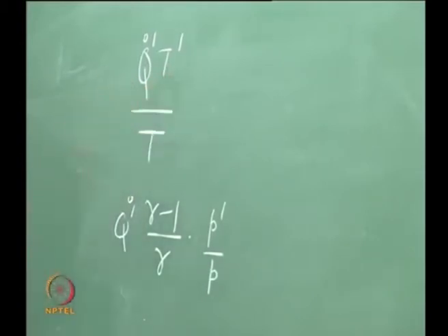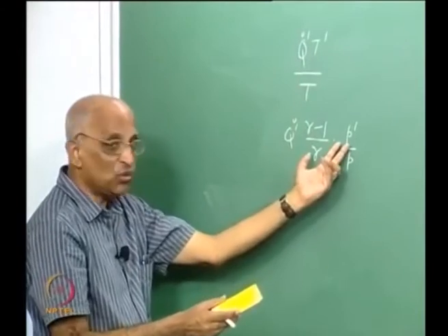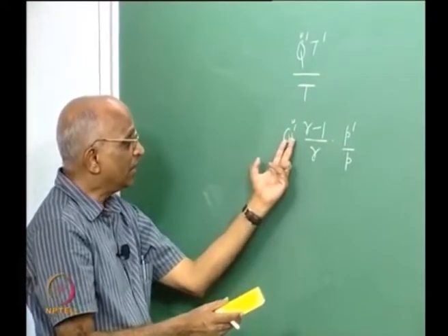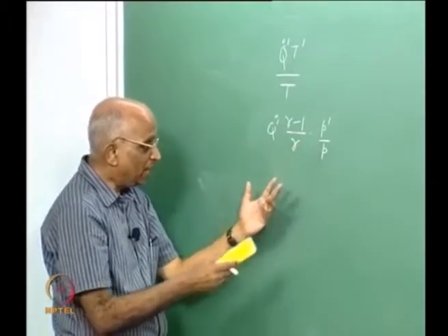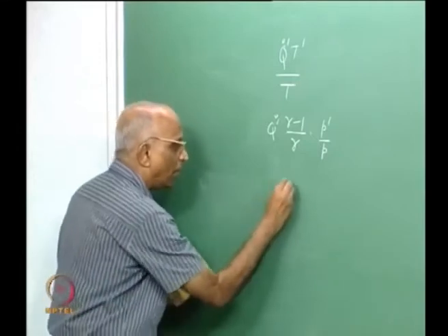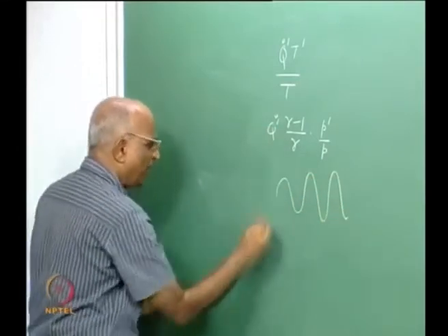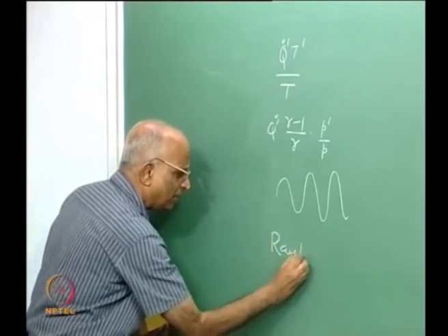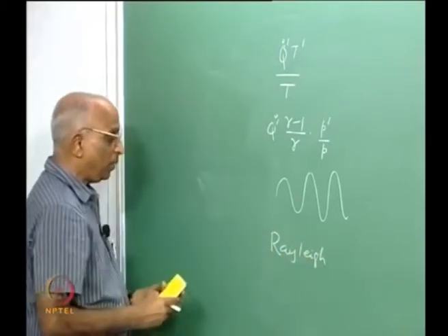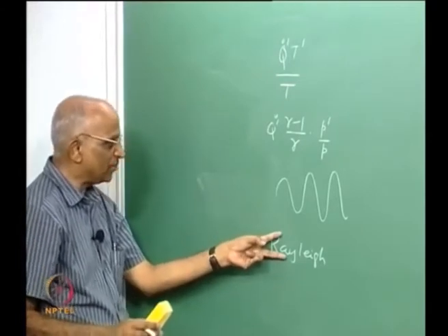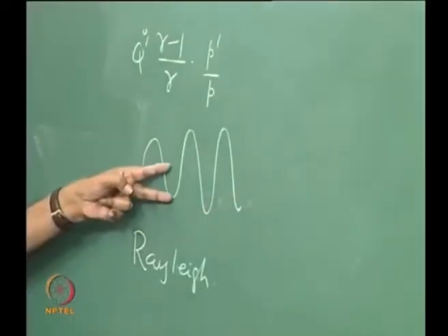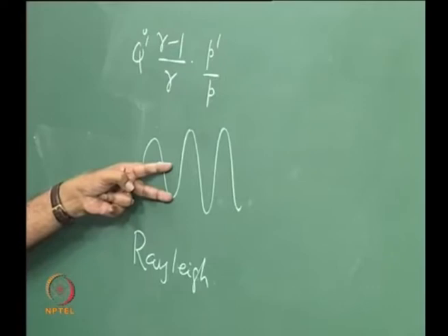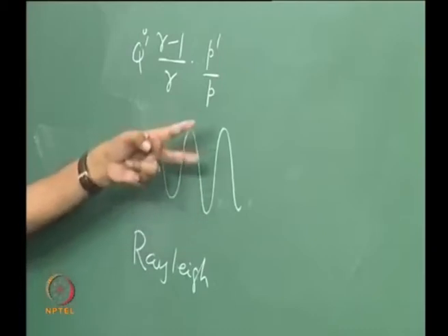Physically, we know when I add heat the temperature increases, but this is not so apparent to us, and this tells us that heat release in conjunction with a pressure perturbation will lead to energy being given to the wave motion, or the oscillations will grow, and this is the famous hypothesis of Rayleigh. It is known as the Rayleigh principle, and all the Rayleigh principle says is, if I add heat at the moment of the greatest compression, or I remove heat at the moment of the greatest condensation, by condensation in the old days it meant rarefaction, then an oscillation will be encouraged.